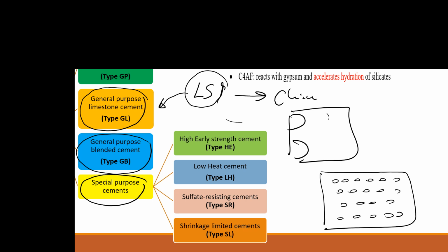That's the only material that, when we cool it down, is expanding. That's the only material, water. All the other materials, when you cool down, are shrinking, and when you heat up, are expanding. So when we have a concrete in a freezing environment, we need to provide the space for water to become ice. So we need to have air entrained concrete, because it's going through that cycle, freezing and thawing, freezing and thawing.